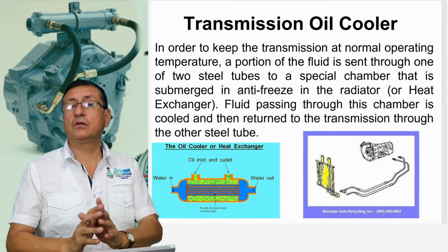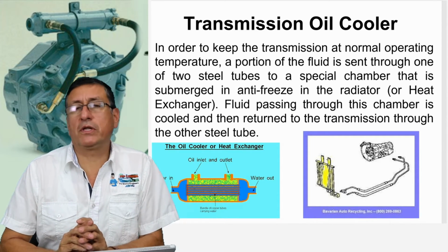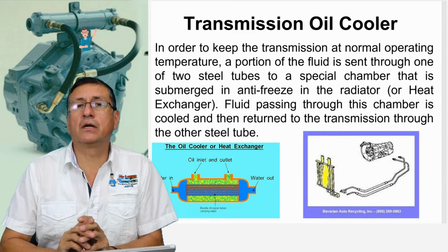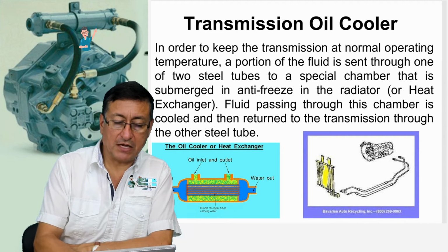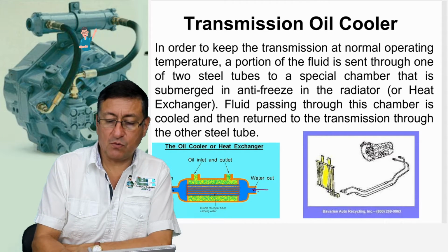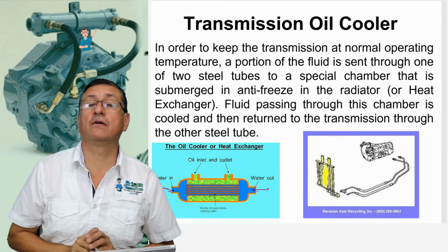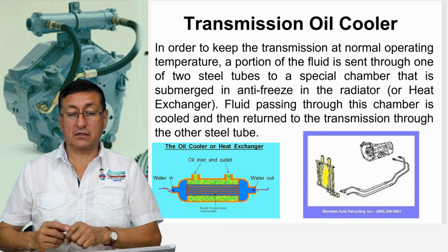In marine applications, the oil goes out into the oil cooler. All the marine transmissions, gas or diesel, use an oil cooler. And of course, the oil cooler has the pass of salt water in the middle, and the oil circulates internally through the pipes of the oil cooler. And both of them are critical.